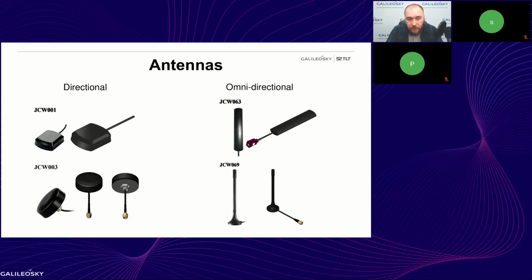If you don't know how vehicles will approach each other, it might be more practical to use omnidirectional antennas. In this case, you only need to think about the placement of the antenna, so that antenna must be installed as high as possible. It might be installed on the roof, if it's allowed by the client, so that again antennas must be in direct view of each other.